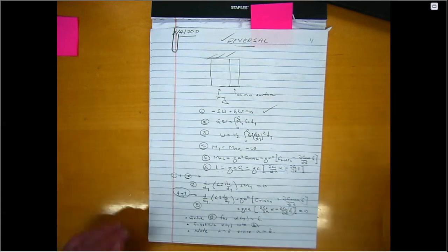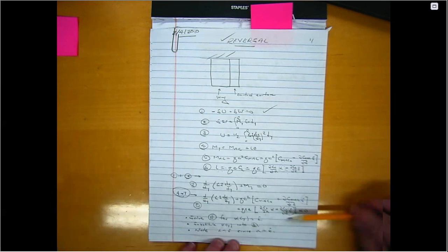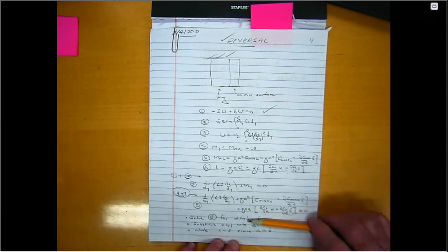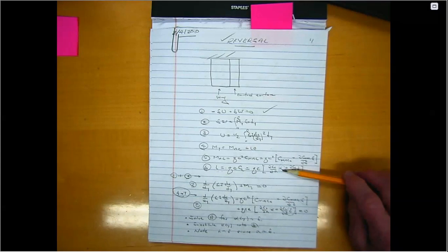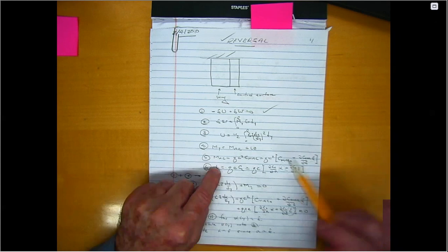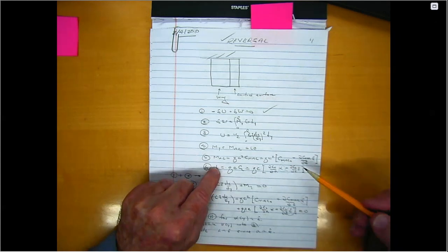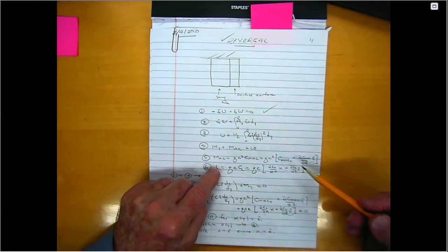Okay. So we need to solve this equation. This is what I told you the other day for alpha. And when you do that, you'll find the alpha is proportional to delta. Okay. Then you need to substitute that back in this expression for lift. Remember, alpha will now be a function of y, but it will be proportional to delta. Therefore, the lift will be proportional to delta. The lift varies along the span, but it will depend on y.